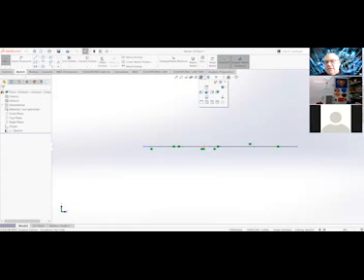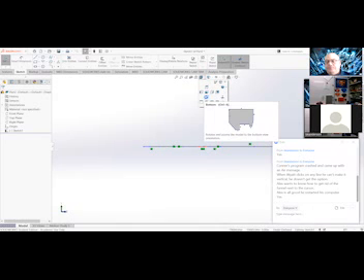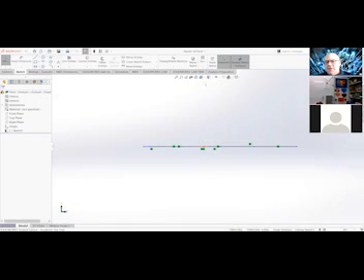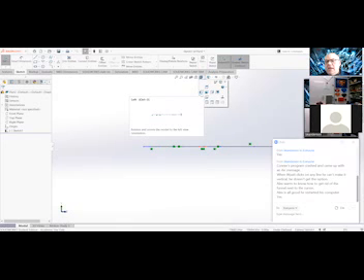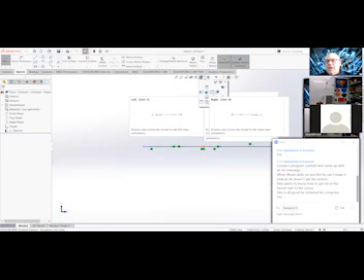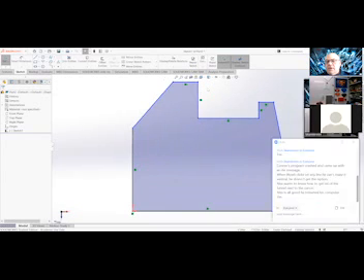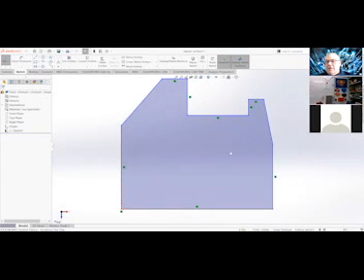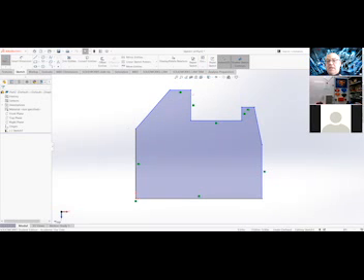So if I'm looking at these little boxes in the middle of my screen now, and we will talk about the other stuff at a later date, there's 6 boxes here. Every object has 6 sides. So I have a top, a left, a bottom, a front, a right, and a back. If I click on the top view, I'm now back to where I was, and everything's right where I left off.